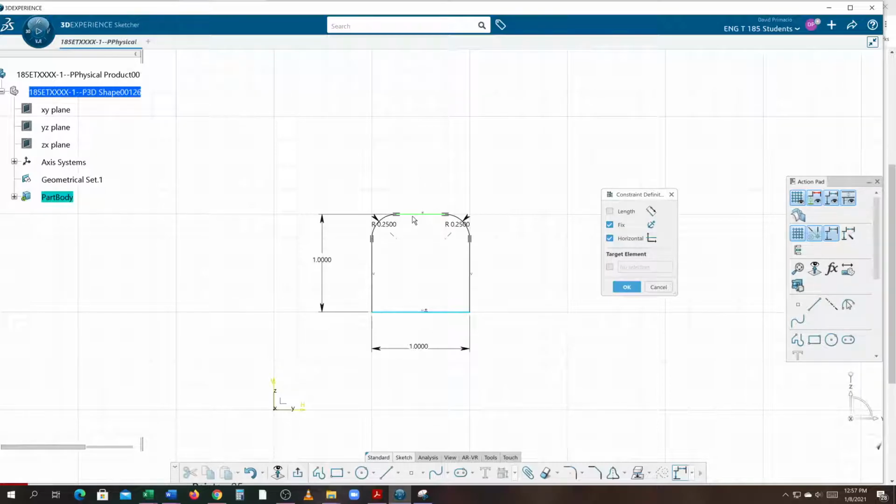This line I know is going to be 1 inch long, and I know not to let this line move, so this will only go in the up direction. As you saw earlier, it went down. When I select OK, unfortunately what happens is there's a little H right here. You can barely even see it, but it turned red. It's hard to see, but we have to delete that H. So I'm going to click on that little H and hit delete.